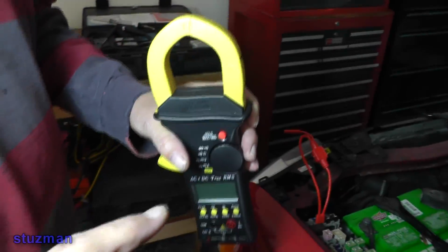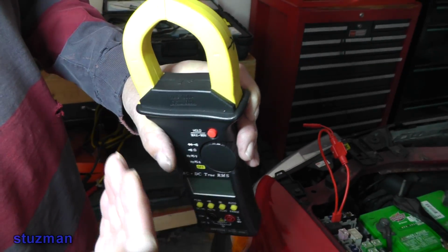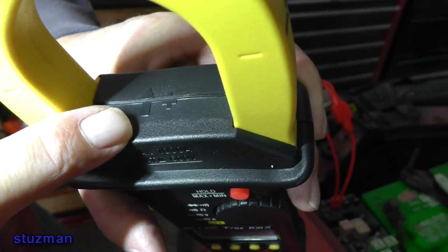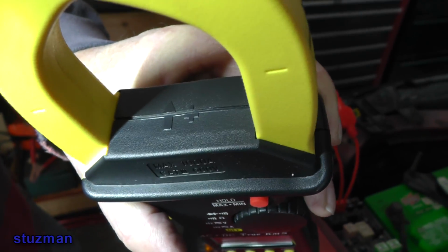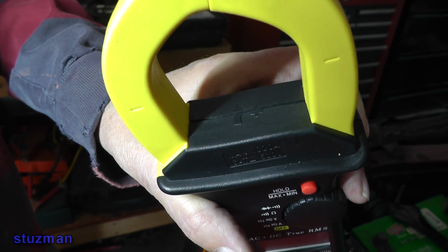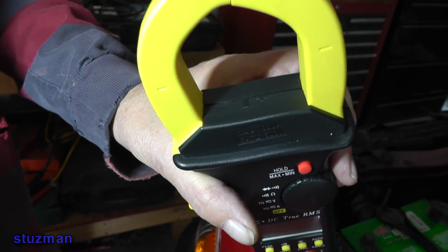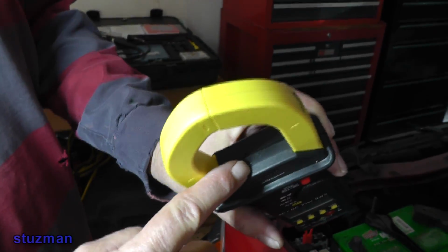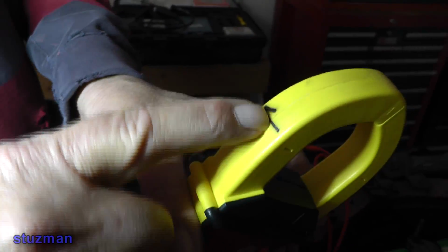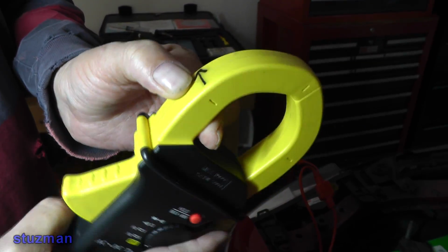All right, now take a look at the amp clamp. I'm leading up to why I wanted to know which side. This way you know which way to put a clamp on. You get it right the first time. If you look inside the jaw, on most amp clamps you'll see an arrow. And if you look up there, you'll see a plus. What this is telling us is it's set up for conventional current flow, meaning that the current is flowing from positive to negative. Now, since this arrow is on the inside, you have to kind of look a little bit, turn it. So what I've done is I took the arrows and I drew them on the outside of the jaws so I could see them right off the bat.